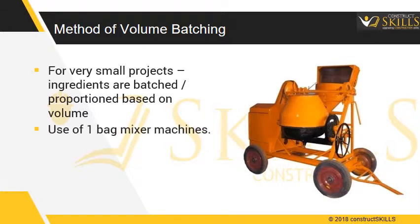Usually it is done through one-bag mixer machines. Under these conditions, accurate proportioning is very difficult. To achieve a reasonable minimum quality of concrete, it is usually less expensive to prescribe an excess of cement than to employ quality control.